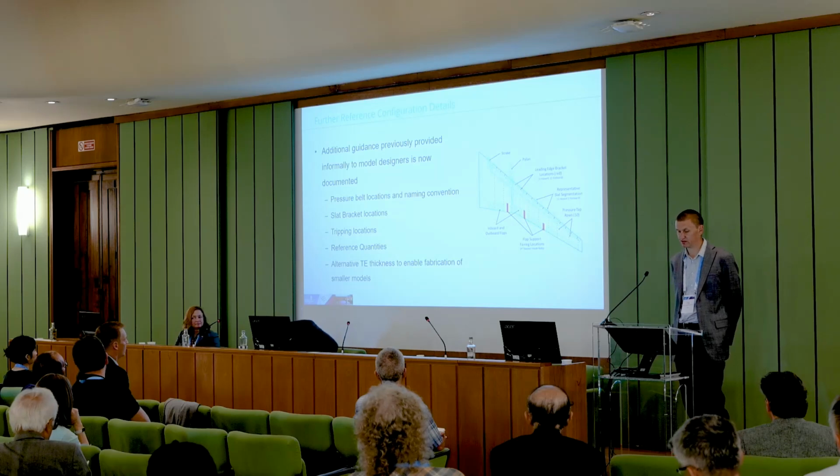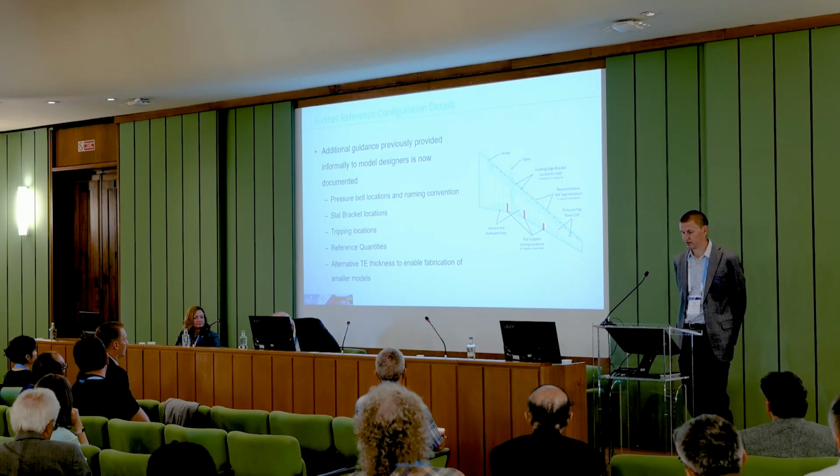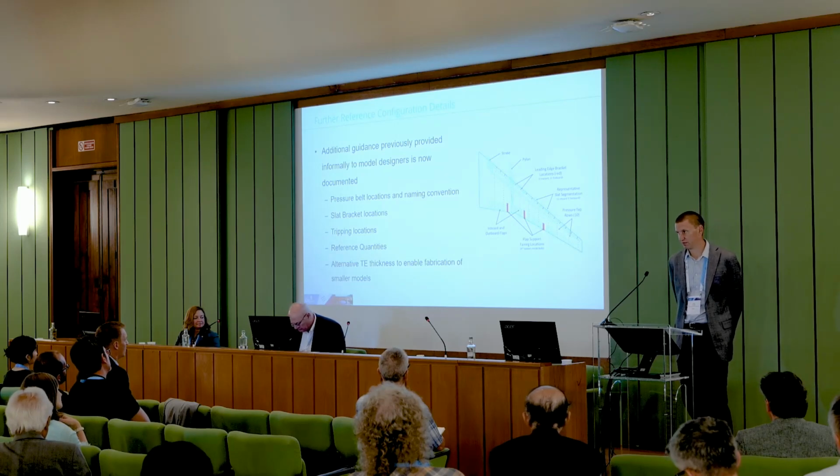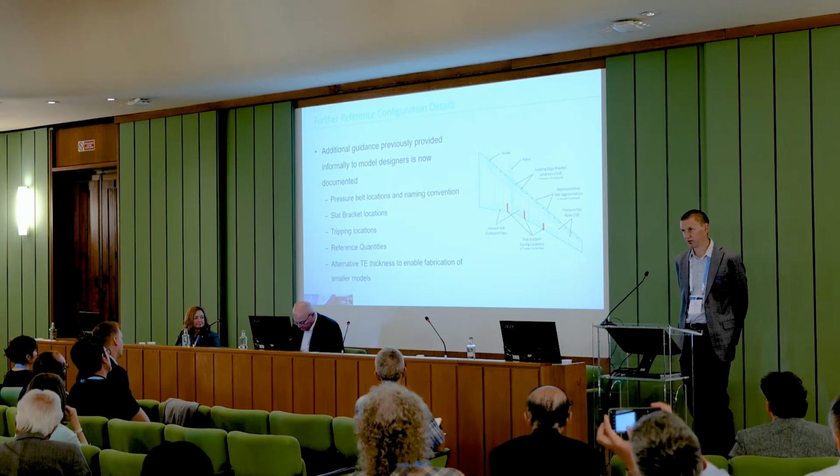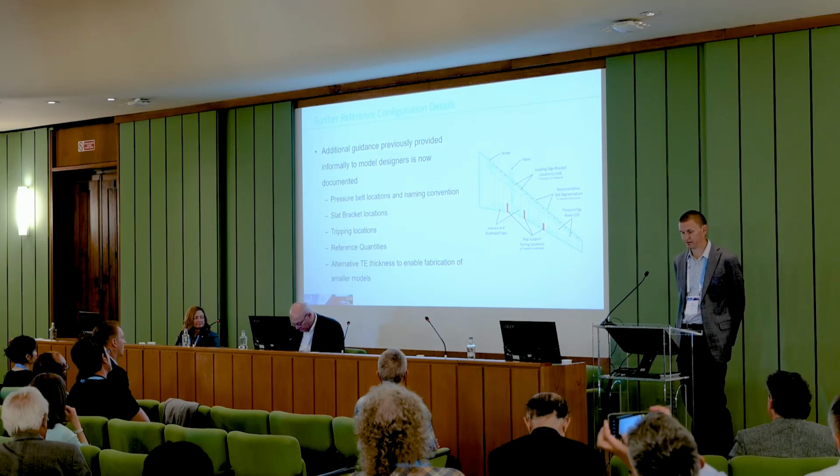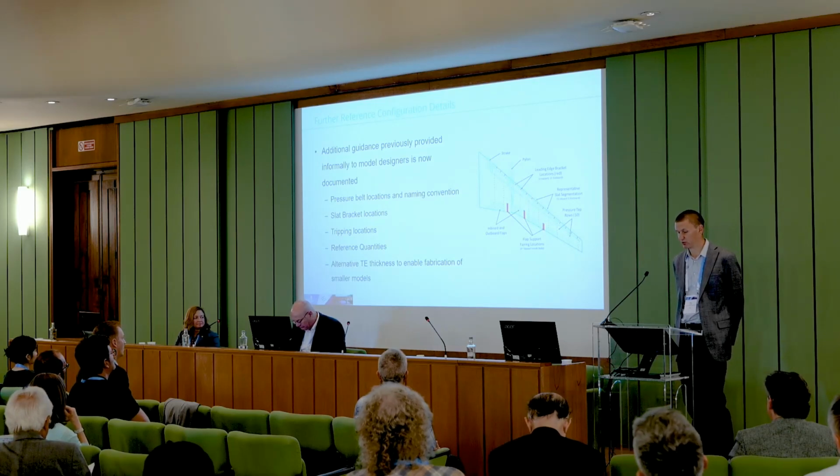The slat bracket locations are explicitly defined here. We've gone forth and put out a set of trip dot curves, so the typical locations where we want the model tripped, and that includes for all possible configurations.